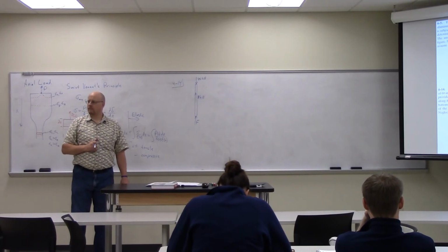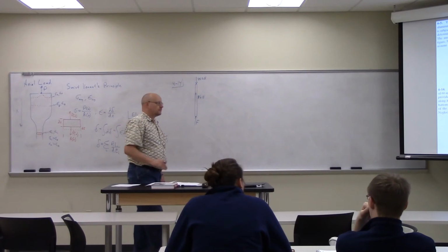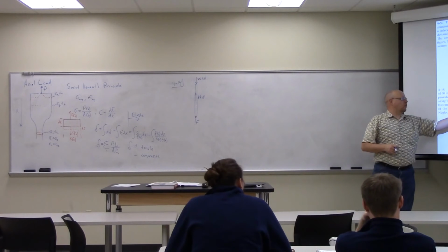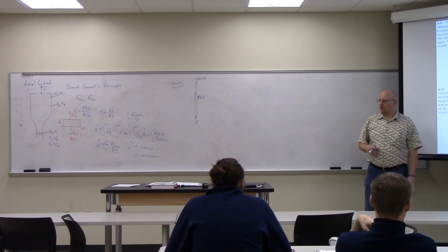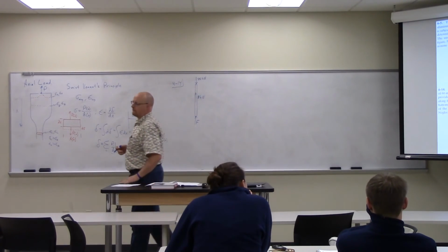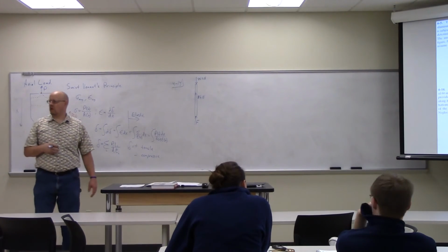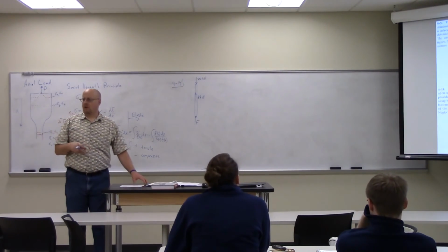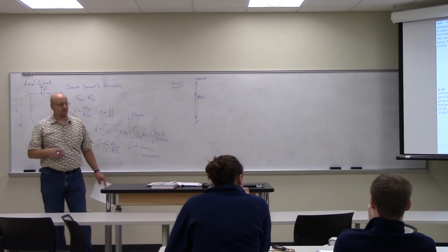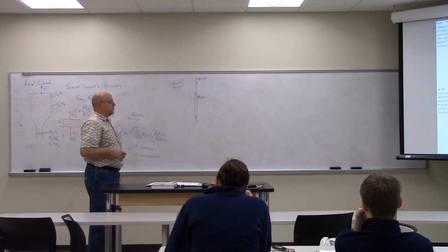Why is it only 4 times 2? Because I remember earlier, when we did the example of pulling the bolt on concrete, they gave us the units of 4 kilonewtons per meter. So they've already taken into account the surface area. If they gave it to us in 4 kilonewtons per meter squared, then they expect us to multiply by the surface area, by the circumference. Okay, that makes sense. Right, so what do we do?